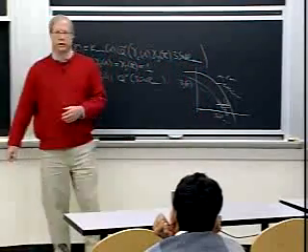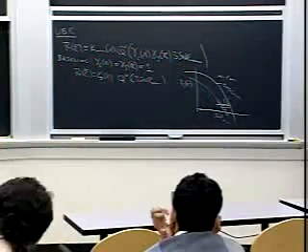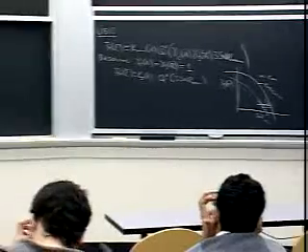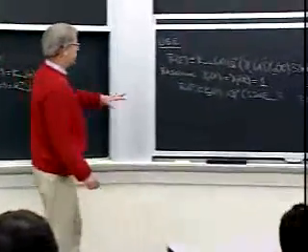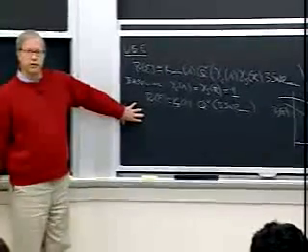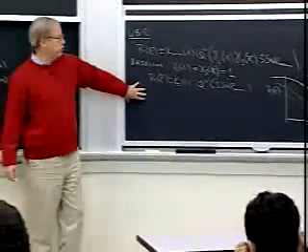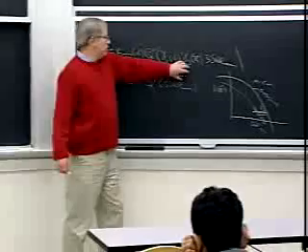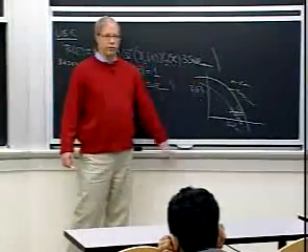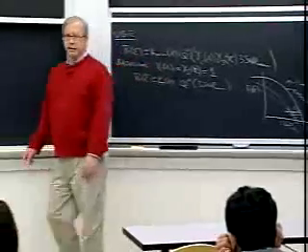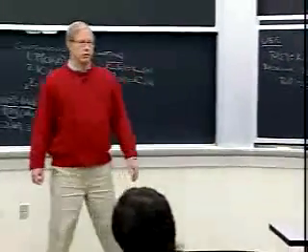But we've basically, by these large constellation, high SNR approximations, really reduced the analysis of lattice constellations to a very simple task. Just analyze what's the coding gain, what's the shaping gain, number of nearest neighbors, plot the performance curve. End of story. Okay? So we'll start there next time.